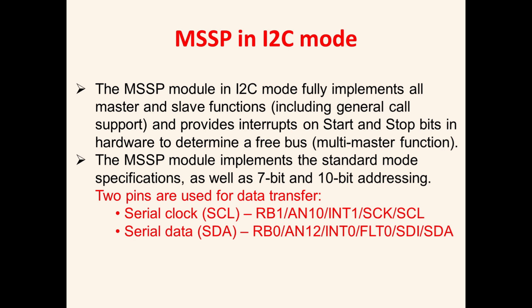Whenever you initiate the communication between your master and slave, it works on the basis of acknowledgement. Let's say you have initiated one slave, so you need to configure the slave address. That configuration with multiple slaves is accepted. Whichever slave is fixed with that exact same address will send an acknowledgement for the address.